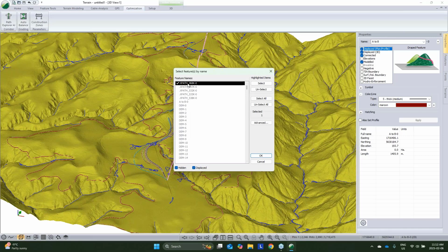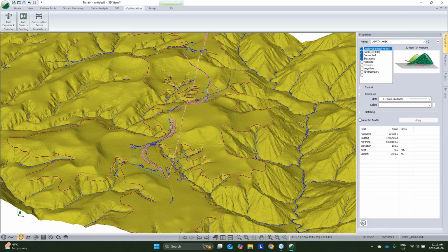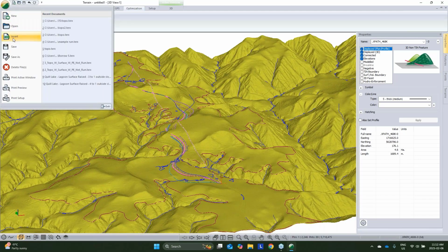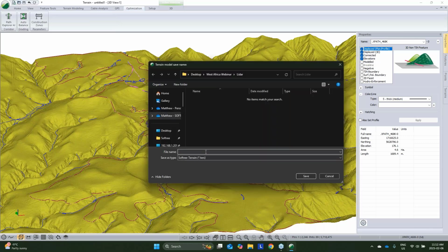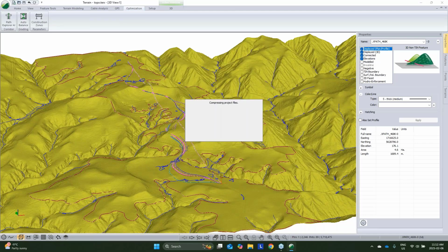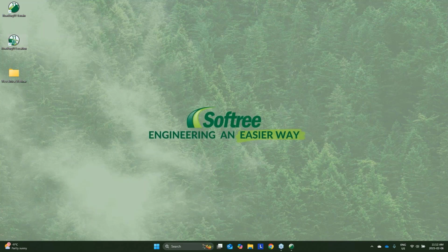and we can see, okay, that Path Explorer feature, the number after is our cost. So that one is our cheapest option. Once again, we can hit save. I'll save this out as a topo, and to take that line on the map and turn it into a proper road geometry with cross sections and all that good stuff.